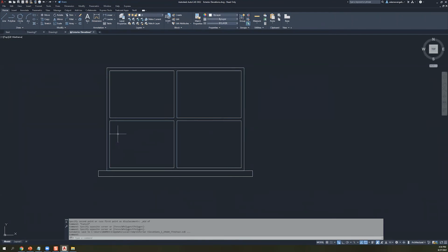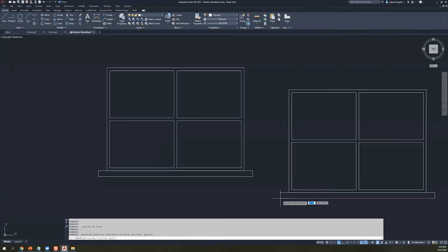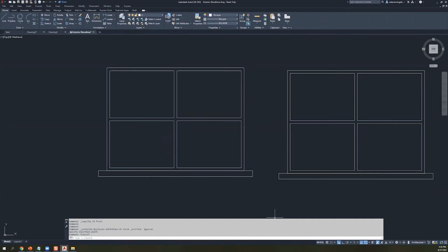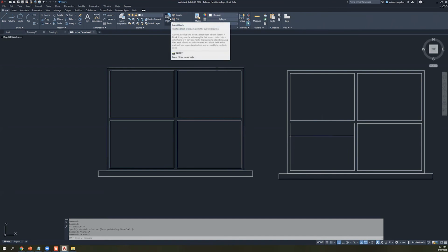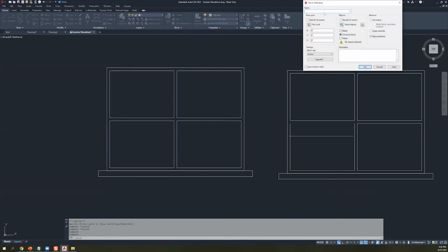And again, now we have a bunch of different geometry. If I wanted to, I could select everything, Control C, Control V, and that's technically an extra window. But there is still a lot of extra stuff here, and I can still break this and move it around, which isn't ideal. What we want to do next is take a closer look at the block functionality available here in the block section. Under insert and the other options, it's pretty self-explanatory: you could insert stuff right here, or you could create or edit a block. What we're going to do is click the create button in particular.